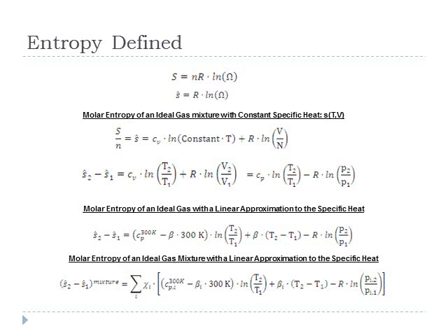Okay, so now in these next equations, we're going to take away one of the assumptions. We're not going to assume a constant specific heat. We're going to assume that the specific heat looks like a constant plus some linear correction term, and that linear correction term is beta. It tells you the slope of the specific heat as a function of temperature.